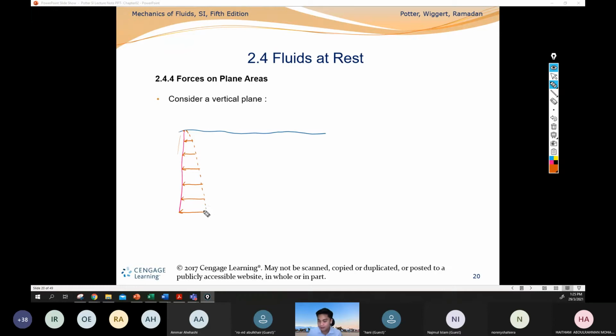So from here, we have the resultant force due to the pressure. We call it the pressure force. Where is the location of the resultant force? Anyone? Is it at the center of the area? One third from the back of the triangle and 2/3 from the front. Okay, normally that is correct, yes, because you measure the centroid of the triangle, right?